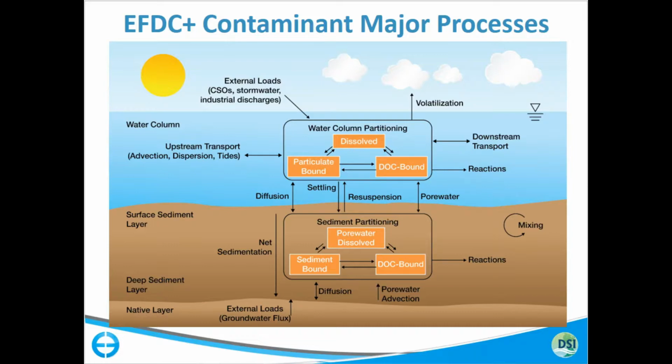We have pore water diffusion in bed mixing, not so much into the water column so much as in the sediment bed here, but you do have pore water diffusion occurring both inside the bed between the layers, and then there's a separate pore water diffusion coefficient for the bed water interface. So you have diffusion processes in the sediment bed, and then at the sediment water interface.